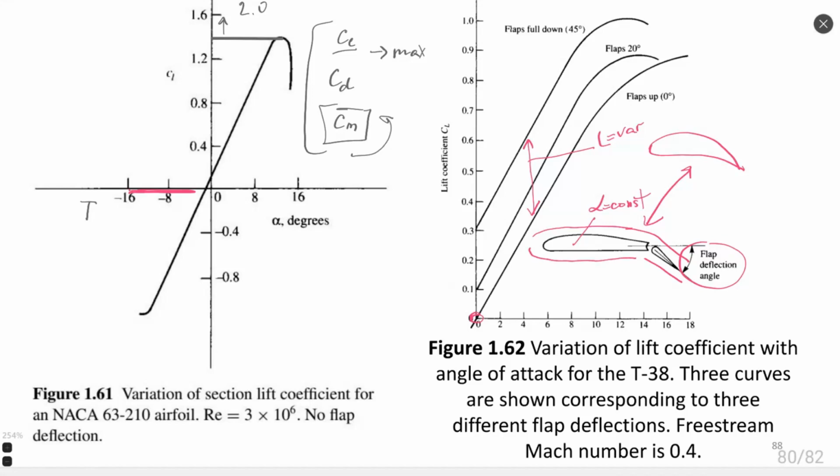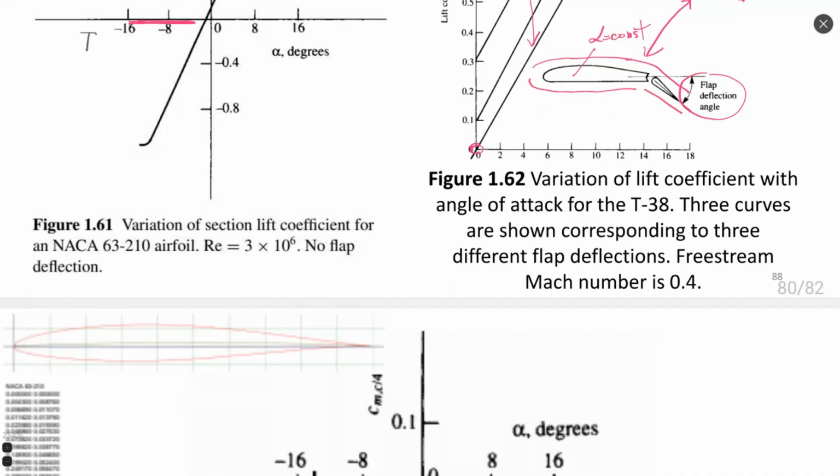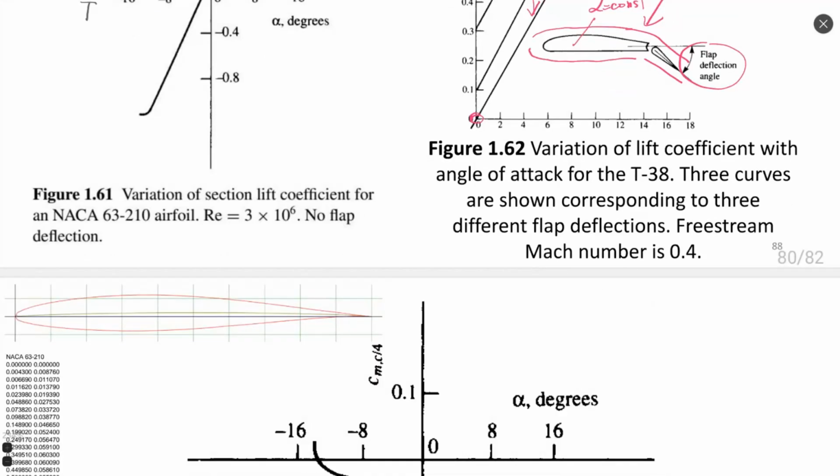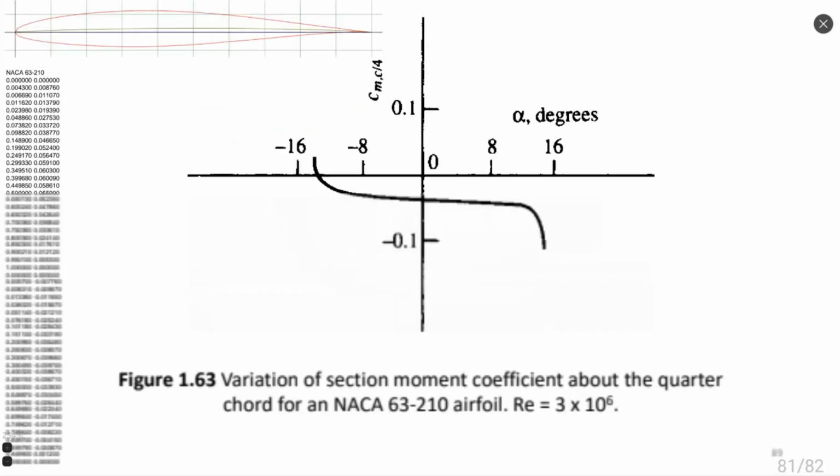That's one of the ways to change lift, right? The most efficient, probably the most performant. Nowadays, a flap is not just a simple airfoil behind the wing. Nowadays, a flap can have a very complex multi-body structure that allows very good efficiency. About this, I think we will talk a bit later when we talk about flow separation. It will be a discussion.